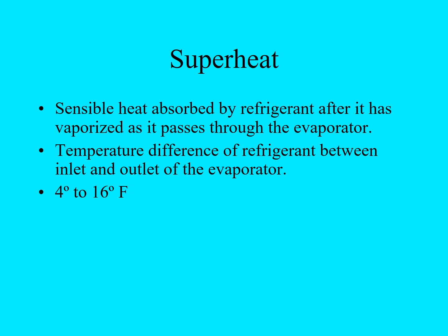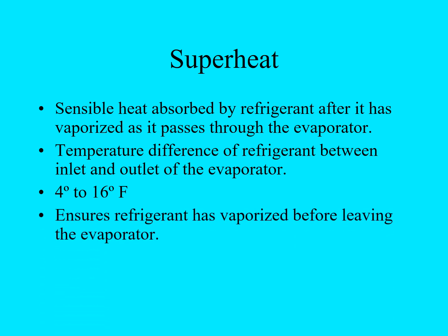That temperature increase could be from 4 to 16 degrees Fahrenheit, depending on the manufacturer and how much superheat they wanted to have take place in the low pressure, low temperature evaporator side of the refrigeration system. And again, this is to ensure the refrigerant has completely vaporized before leaving the evaporator.